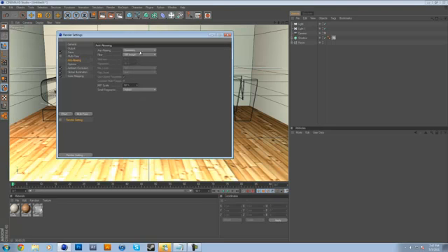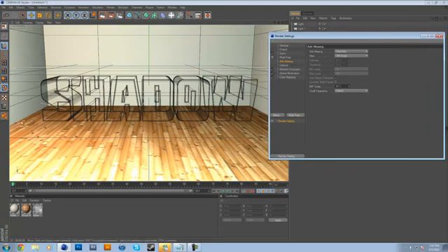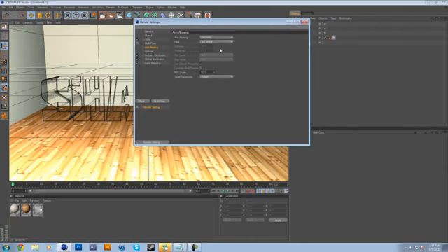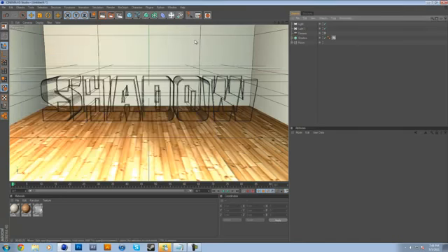We will actually have to pop up our anti-aliasing for the glass texture, because glass, if you don't have your anti-aliasing on, you get real jaggedy edges. The reflections won't look very solid at all. It'll be rather hideous, to be honest. So we'll go to aliasing best, filter still image of course, and I'll keep it at about 1 by 4 by 4. I'm going to need it quite high. So that is about it.